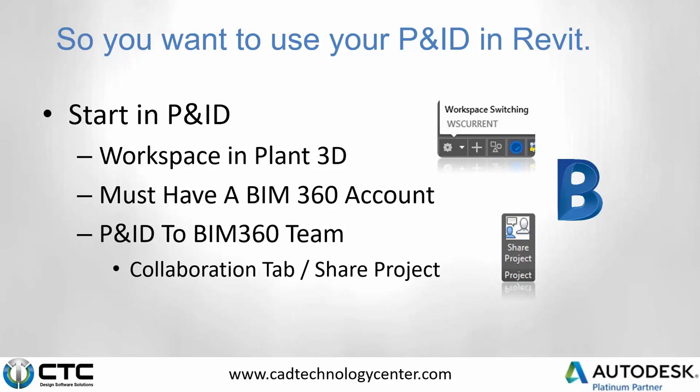Another thing that's important is that in order for this process to work, in order to get your PID into Revit, you have to have a BIM 360 team account. You have to either have one personally set up or have one set up through your business, because this process does work through the BIM 360 hub. It is a cloud-based process, and we have to be cognizant of that and make sure we have the setup done properly.